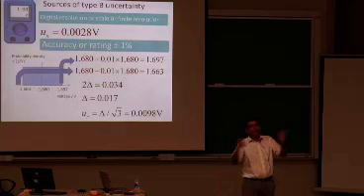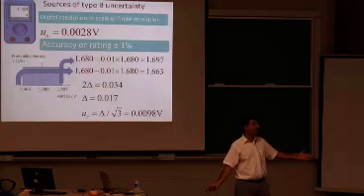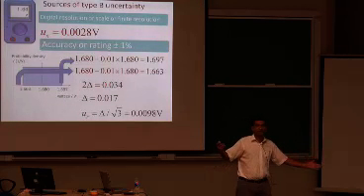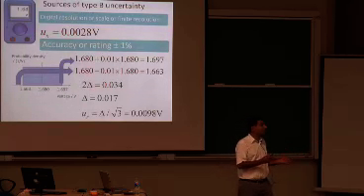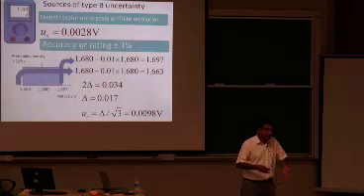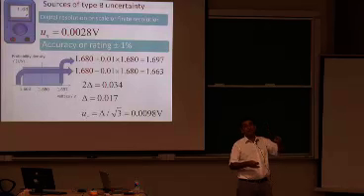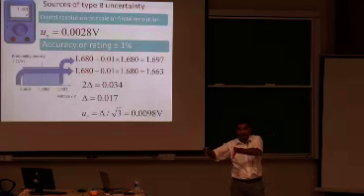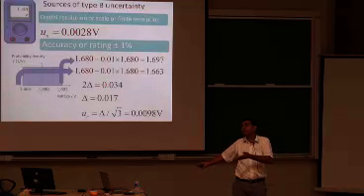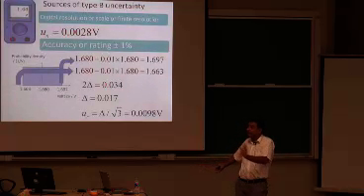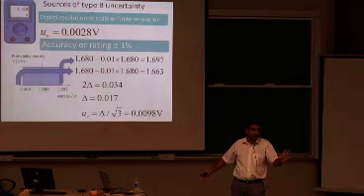This means that whatever reading you measure, you can have an uncertainty of plus minus 1%. So now we would like to associate an uncertainty with this accuracy. We have an uncertainty associated with the digital scale or the finite resolution, but this is another source of uncertainty. And both of them are type B because they are associated with a single reading. We're not repeating our experiments.